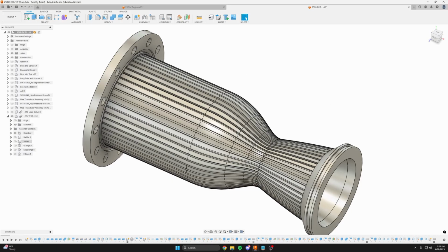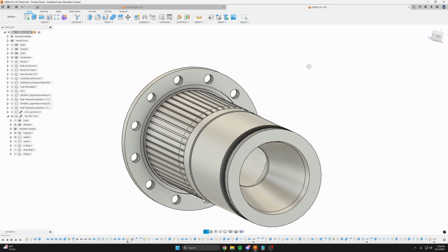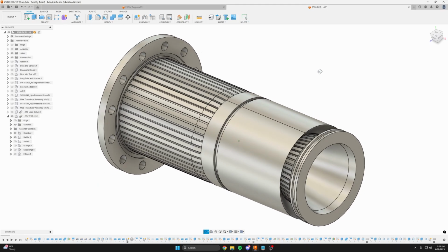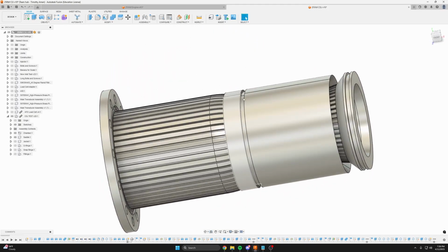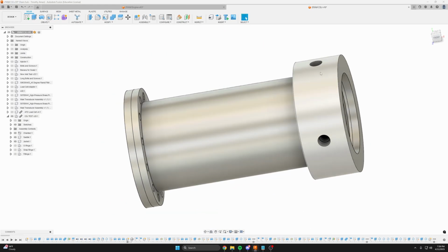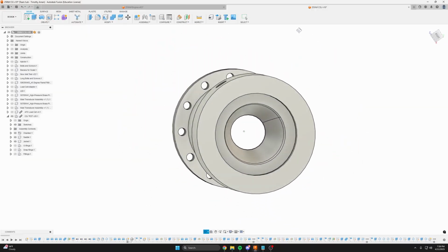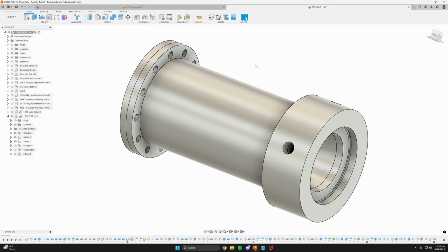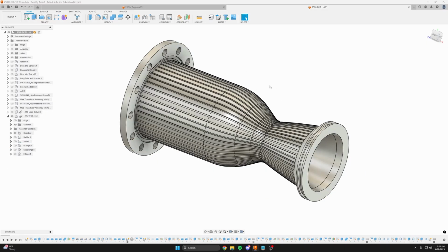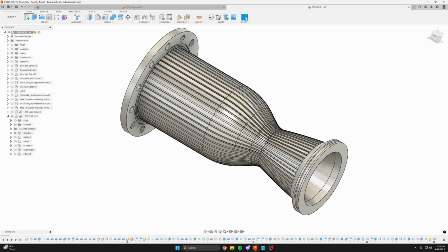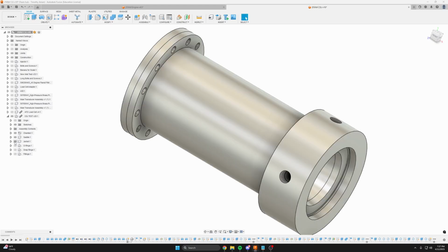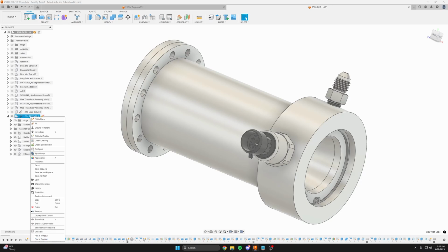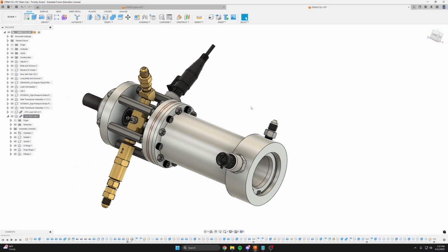And then you just add this part, called the saddle, that goes over the throat and makes it nice and cylindrical, and then the jacket closes it out. This can be machined pretty easily on a lathe, or even printed if you really want to. But the nice thing about this is that there are no small spaces for the powder to get trapped in. You can just brush it out of these open channels and then close them out later. Of course, you pay a mass penalty, but that's one way to get around the problem.